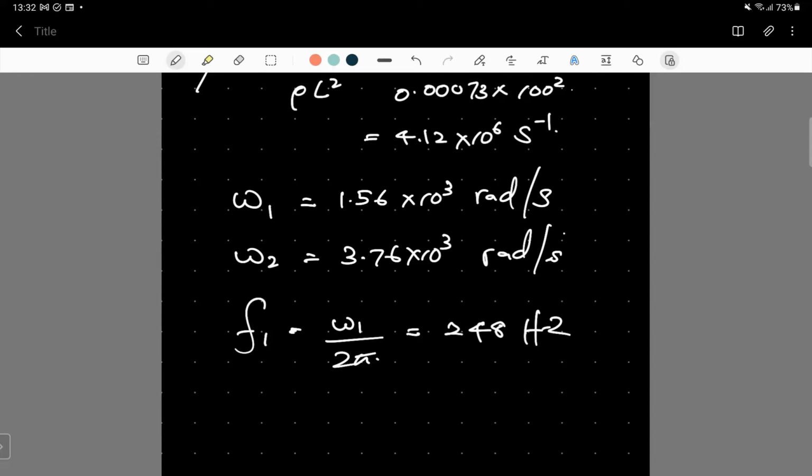So when the system vibrates with the natural frequency omega i, that unique shape with an arbitrary amplitude corresponding to omega i is called the mode of vibration. In general, we know for n degrees of freedom, which has been discretized, there are n natural modes and frequencies. So a continuous system actually has an infinite number of natural modes and frequencies.